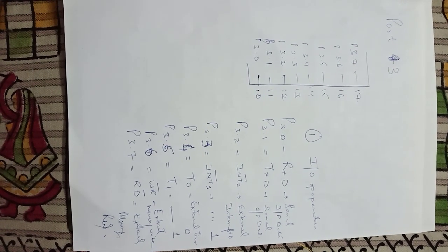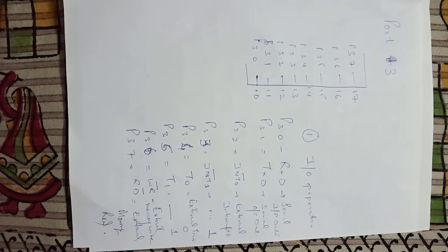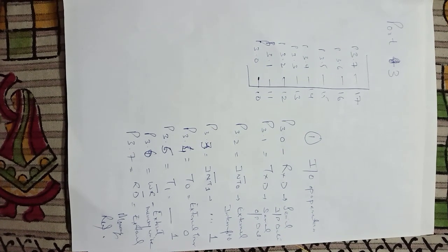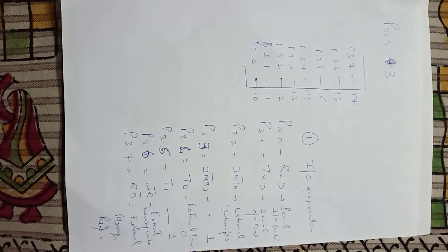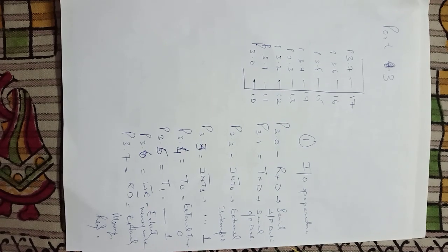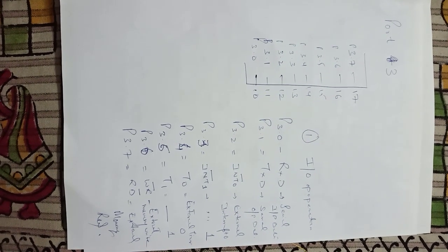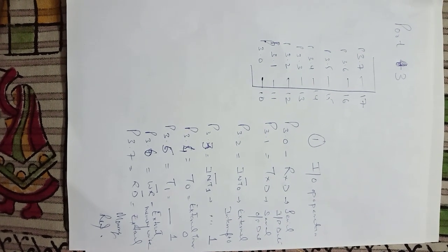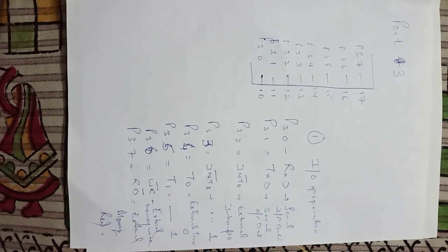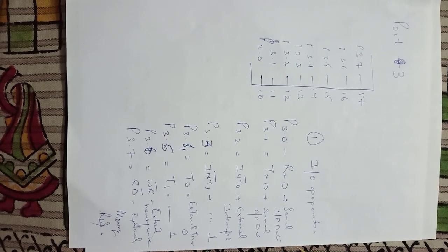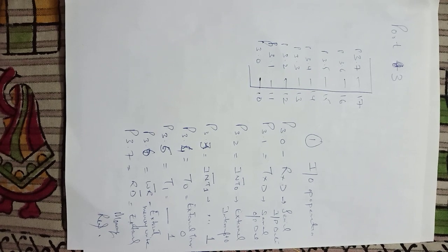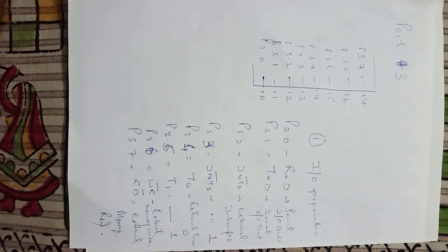Pin number 12 is P3.2 and it is used for external interrupt 0. Similarly, P3.3 is used for external interrupt 1. P3.4 and P3.5 are used for external timers, that is T0 and T1.